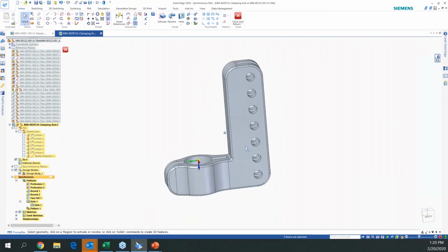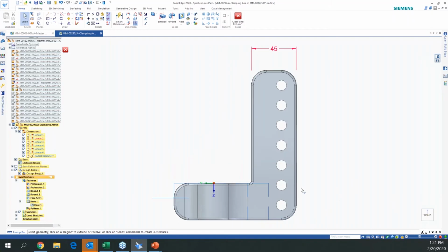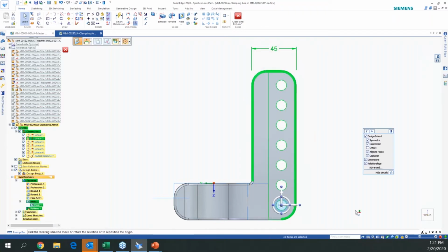All right. And then if you notice here, I can turn on my PMI a little bit, turn that back on. Let's look at my front face, because now that part is pretty much 90 degrees. And I know when I was designing it, I had to give it a little bit of design change. So I can select this little area, just what I want to change. Okay, it gives me my steering wheel. If the steering wheel was at a different hole, I can move it around. So say if it was over here at this hole, I can move it down to wherever my pivot point is going to be.